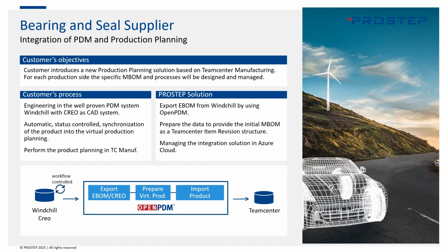Teamcenter was introduced for production planning so that they could do manufacturing bill of materials and future manufacturing operations. So OpenPDM in the middle was able to export the part structure, export the Creo data, create JT that's used for Teamcenter, transform it into an MBOM, and then import that into Teamcenter so that the manufacturing engineers could move forward with that.